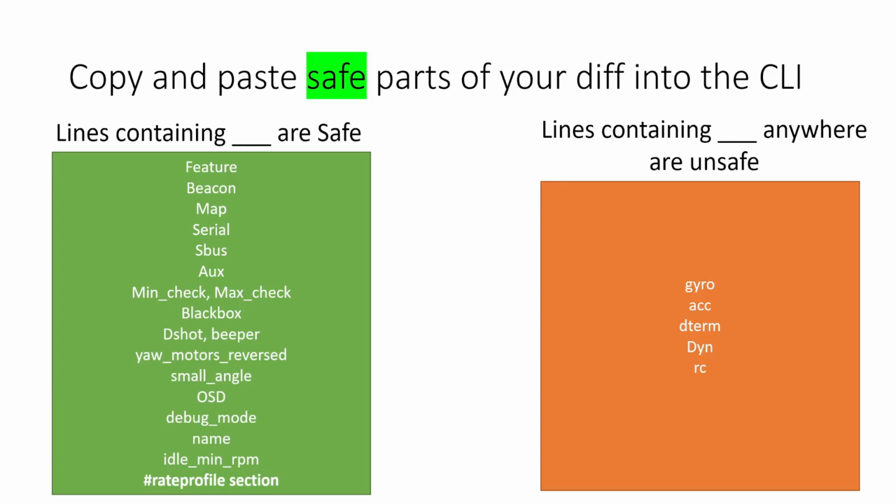You need to be very careful when copying and pasting diffs between different versions of Betaflight. Sometimes settings that worked well in a previous version of Betaflight can cause big problems in a more recent version. And sometimes the names of settings will have changed between versions.